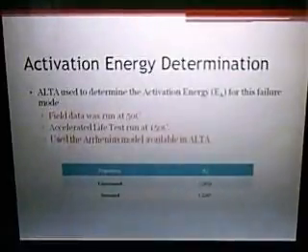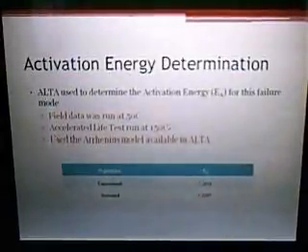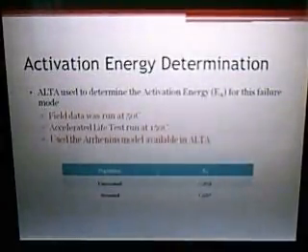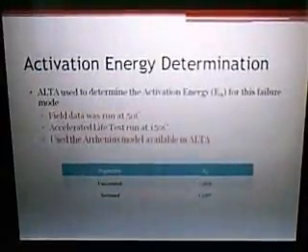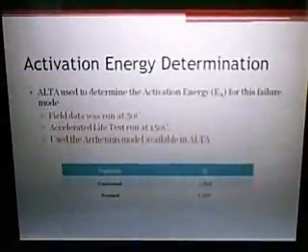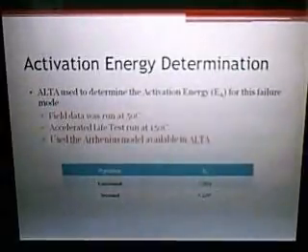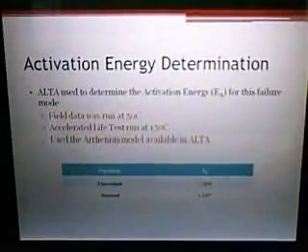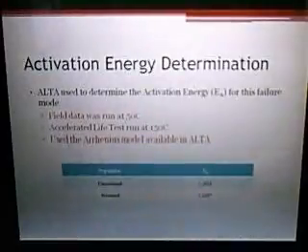This is quite interesting and surprising to us. Well, not so much surprising to us, but it confirms some suspicions that we had, that this particular data set from company XYZ does not demonstrate intrinsic type failure modes for data retention. Since the activation energy during our literature review was 0.6 eV, and we see here from the actual field data for both populations that the activation energy is doubled.